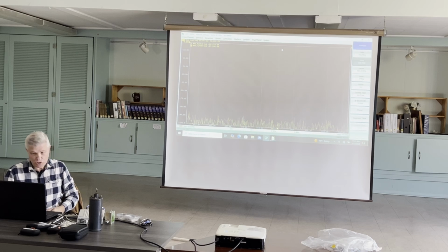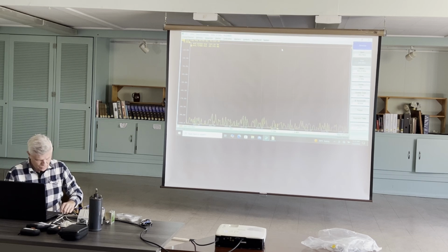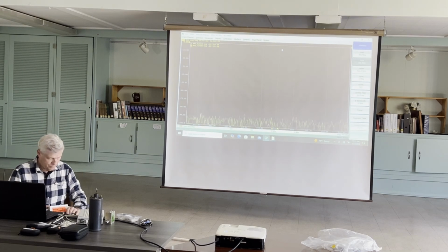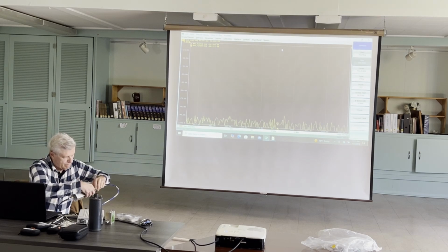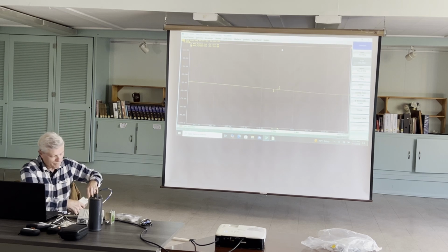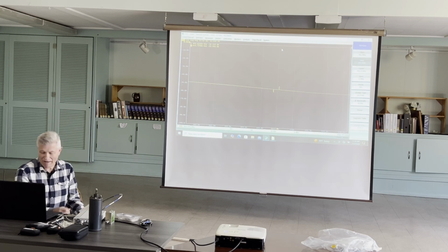Now, technically, I should be recalibrating the instrument. Well, actually, no, that's not true. I have it calibrated for down to 1 meg, so we should be okay. So we'll put port 2 on the output, and we'll put port 1 on the input. Got to be careful with these cables. When I say they're expensive, they're hundreds of dollars each, and the cal kits are even more.